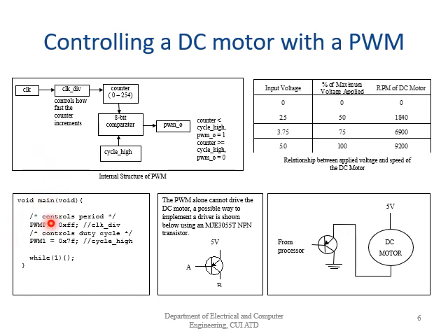So if we want to have 4600 RPM, what we have to do is put PWMP, that is the period, equal to 0xFF for clock div, and now for duty cycle, PWM1 is equal to 0x7F. This while loop will continue forever. So the motor will run at 4600 RPM. Let's pose another example.